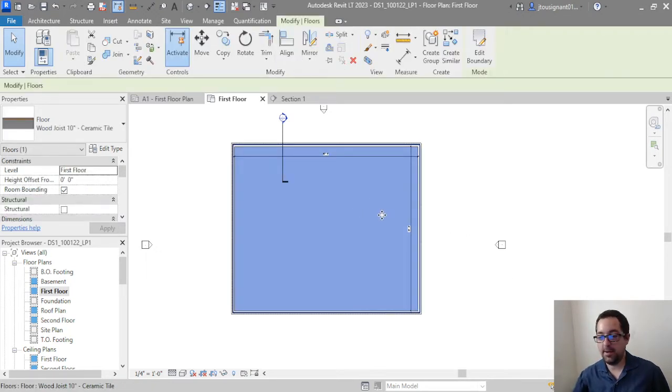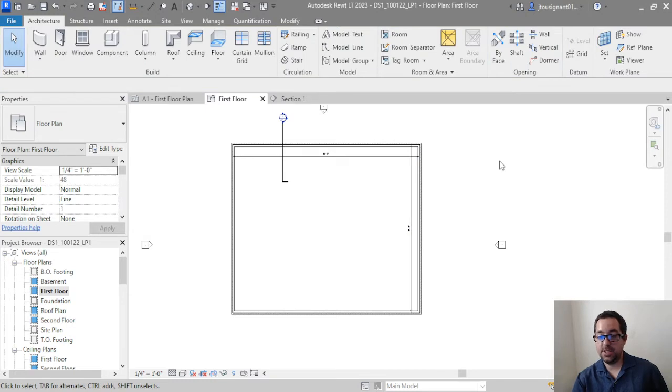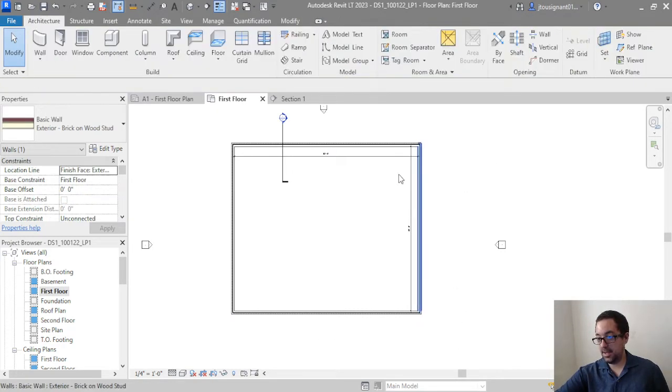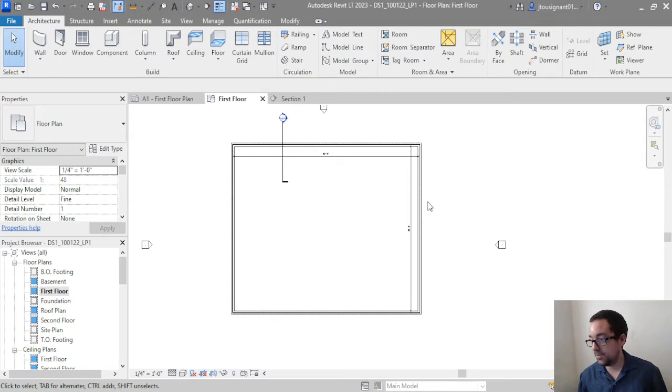and that's going to help you select faces without hatches. And I say faces without hatches because I'm going to go over ceilings at some time, and in those are reflected ceiling plans, and the reflected ceiling plans are going to have poches that are going to represent the ceiling types, and one of the most common types that have a poche or a hatch in it is the 2x2 and 2x4 acoustical ceiling tiles. And those are nice in the same way that curtain walls are nice because they'll have line work in them that allows you to select them. So that's a little tip to help you select those surfaces.